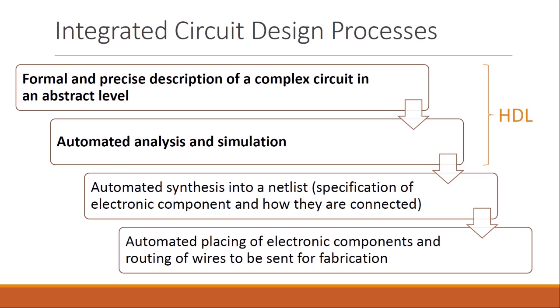Now before implementing this circuit, the first thing you need to do is synthesize it into a netlist. These words like synthesis might be new to you. The synthesis process is a process that we use to generate a circuit out of a model like one described in HDL. When you go into details of HDL, you will understand it better.